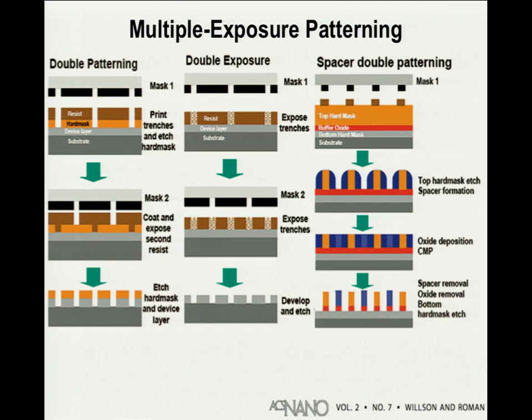Another cheat is to use methods of edge lithography, where, suppose you want this very high resolution pattern, but you're starting with a much lower resolution pattern. What you can do is create features in this resist film, and then deposit some spacer, which could be some oxide or some polymer deposited by chemical vapor deposition or something, and those sidewalls become the new resist features.